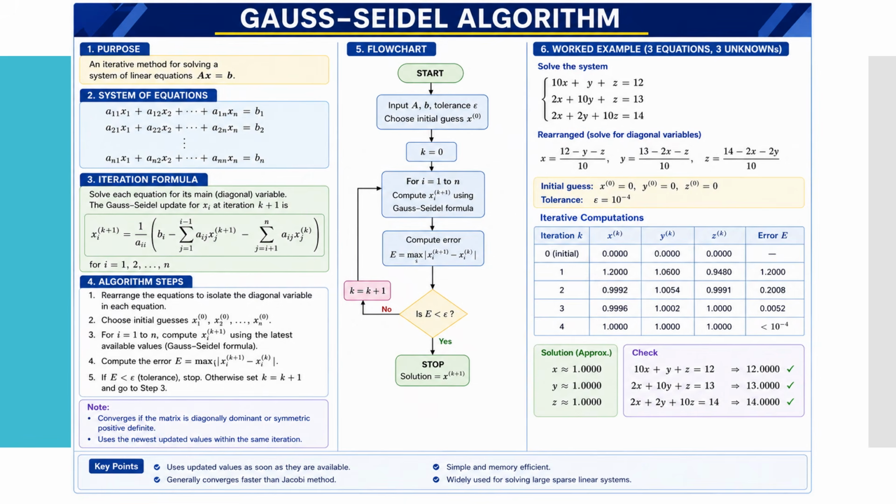Especially when we are calculating a voltage and current relation using a simple linear equation, Gauss-Seidel is the most efficient method to calculate the voltage and the current using an iterative method. Gauss-Seidel is used for a linear equation of the form AX equals B, where A is a matrix, X is a variable to be determined, and the parameter B is a constant.